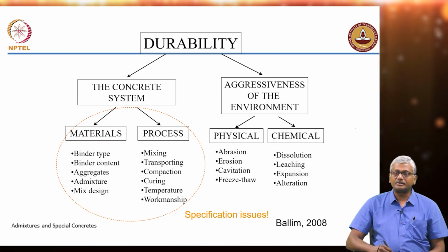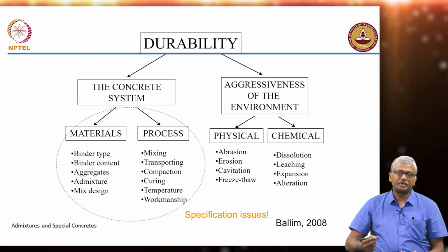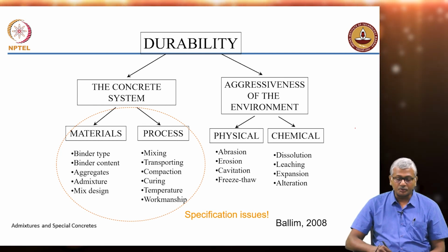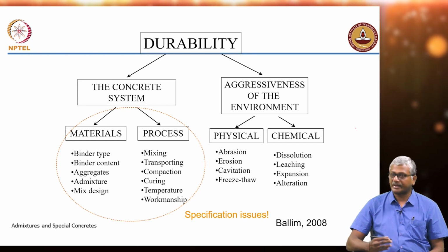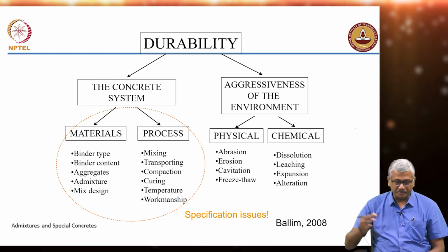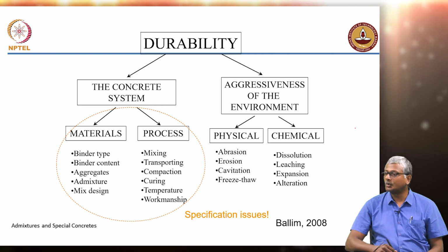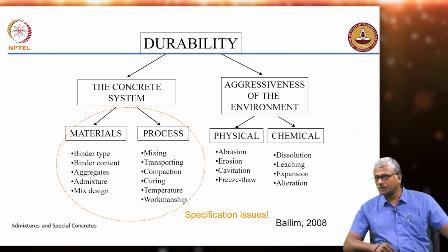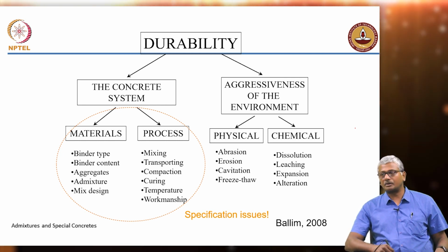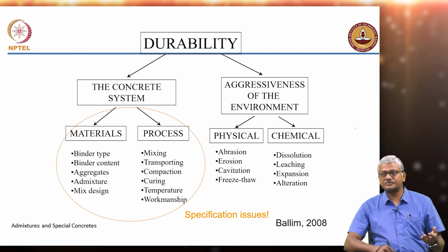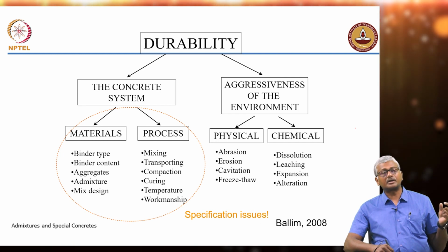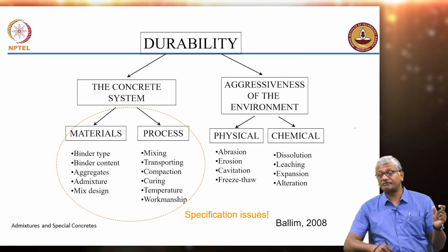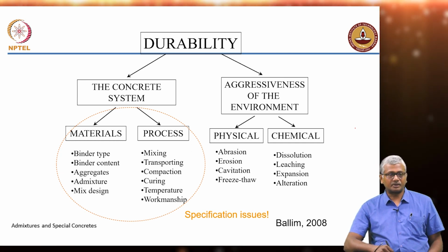Now, coming to the other long term aspect of concrete, it is durability, okay. You design concrete considering the types of materials to be used and the process of actually putting the concrete together, which includes mixing, transportation, compaction, curing, temperature, and ultimately the workmanship, right. All of that goes into actually describing the properties of the concrete. If you do not cure well enough, as we discussed earlier, strength may not get affected significantly, but curing is definitely affecting the durability of the concrete.